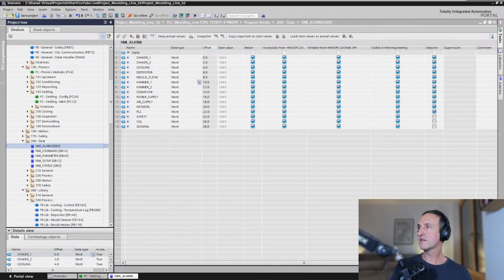As you said, in-out variables have a difficulty in troubleshooting. I use them a lot. Can you elaborate more? Yeah, as I said, Chris, put them as separate inputs and separate outputs. It doesn't make a difference to the structure. So the modular structure you would build anyway, and then you would add them as separate inputs and outputs instead of in-out. You lose a little bit of performance, but whether it's going to be noticeable, I never did the tests comparing everything as inputs and outputs to everything as in-outs.